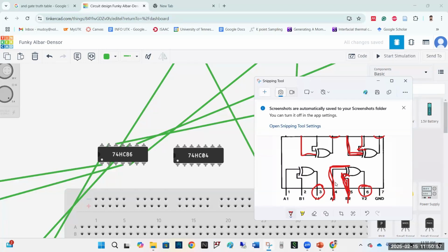If you take electrical engineering as your major, you will deal with this. It will be easier for you if you print them out, because you have to deal with multiple ICs. So you print them all out, keep them in front of you and just compare them. Because at this point I will need the pin diagram of both ICs, as I will connect the output of the first IC to the input of the next IC. So we need to know the inputs and outputs of both ICs.